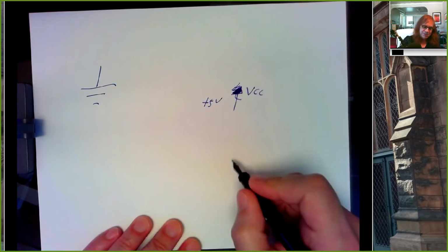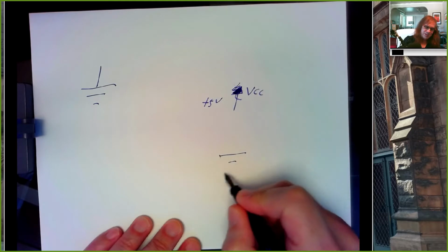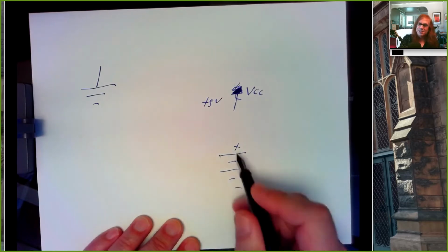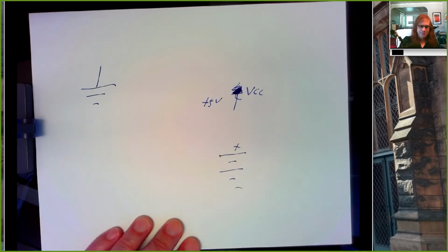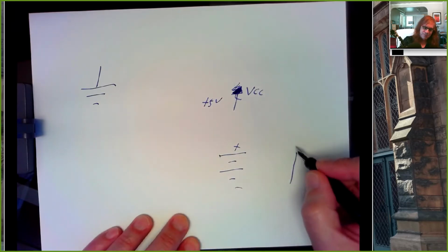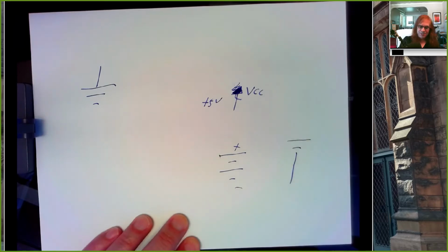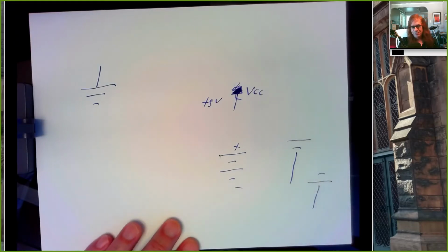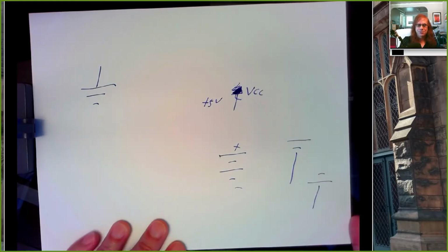The other thing is, sometimes in 120 especially, we draw a battery symbol like this, and that's positive and that's negative. But that is not an acceptable symbol for VCC. And I'm seeing circuits where people are doing this to mean VCC, or worse, doing this to mean VCC, and that looks a lot like ground, right?